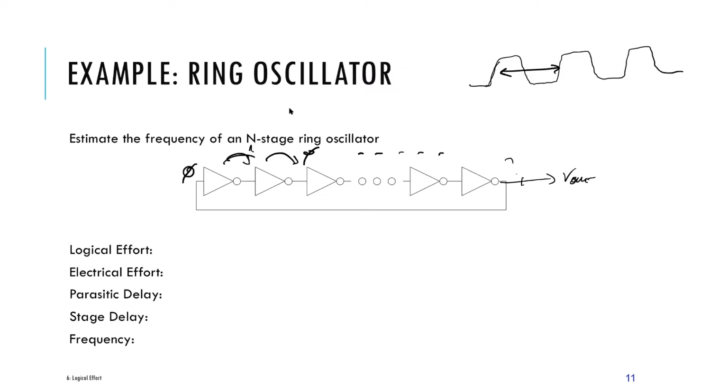People use these ring oscillators all the time for looking at the behavior, like the speed of a process, because this delay is fairly long, since you're going through 31 delay stages, okay? And because you have to invert again, it's like 2 times 31. So if this was a 31 stage oscillator, the period would be times 2, because you'd have to carry a 0 across and then come back with a 1 across before you get to 0 again.